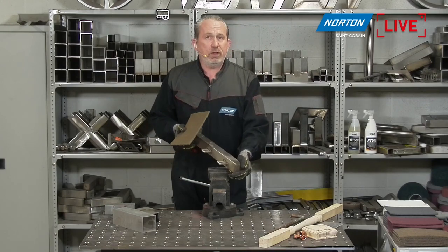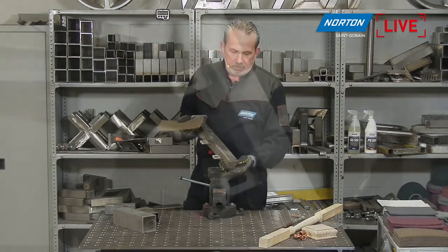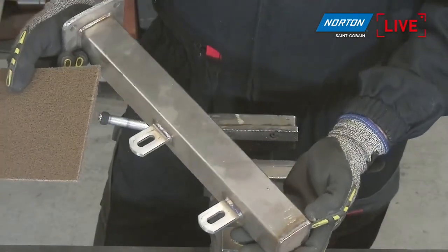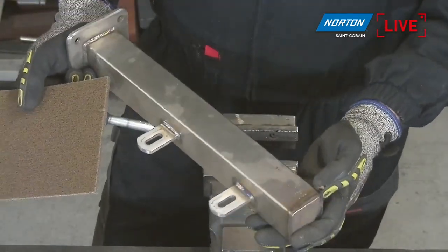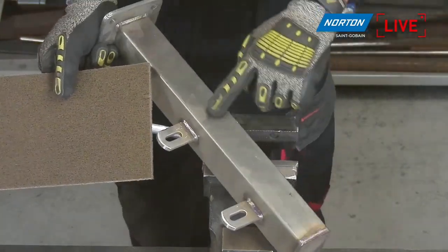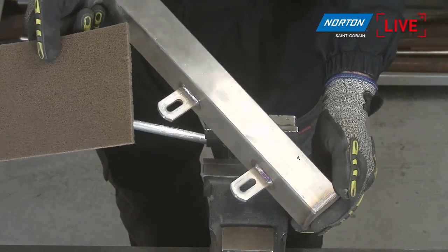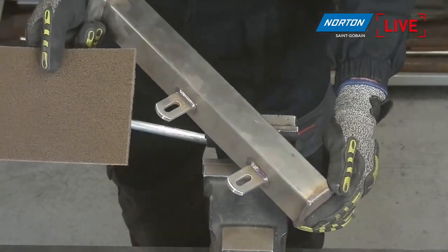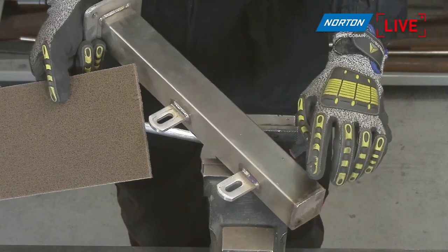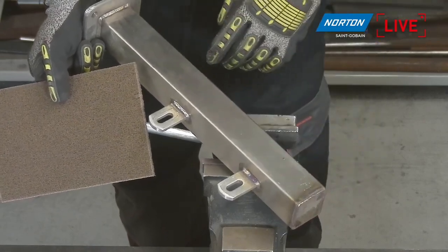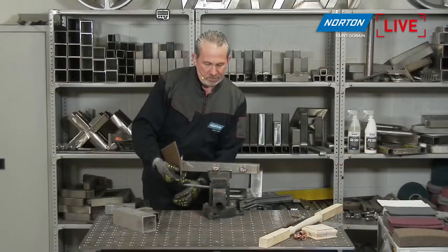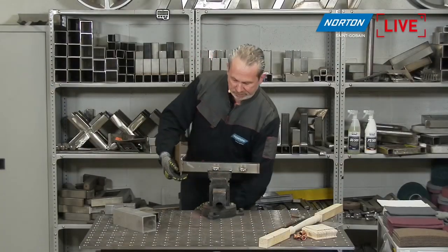Robin, what we're going to do then, we're going to have a look at sanding down this bit of stainless steel here. So this is like a welded piece of balustrade or fencing, and you can see we've got some weld burn at the end here. But we've also got lots of scratches on the surface. So what we're going to do is take out a lot of these scratches and damage and give it a nice uniform linear scratch on the surface, all using this single hand pad, the heavy duty. Let's get that in the vise.